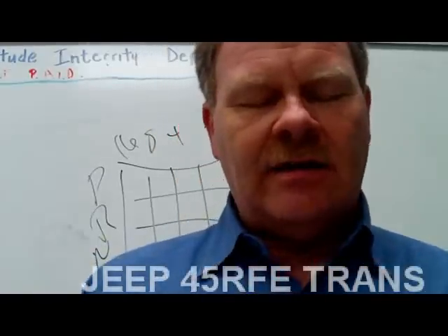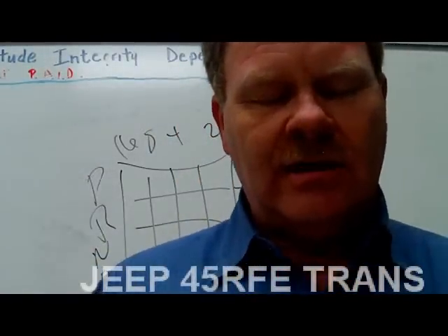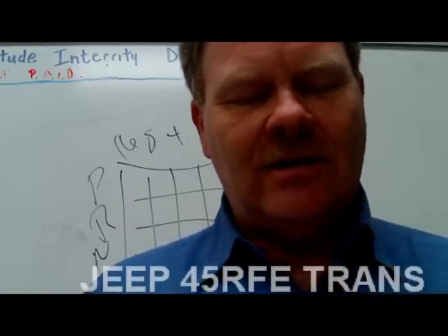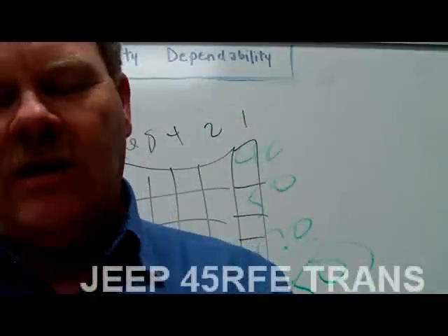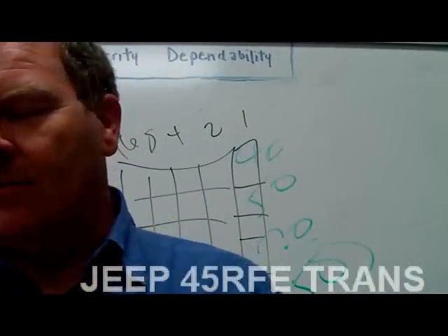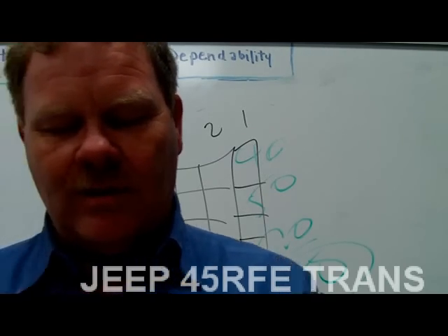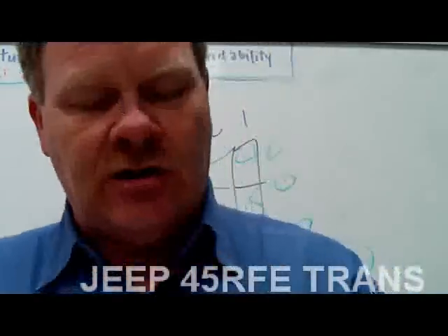All right, the solenoid pack of the TRS assembly consists of the transmission range and temperature sensors, pressure switches, and shift solenoids. The solenoid pack TRS assembly utilizes a 23-way electrical harness connector to link up with the transmission control unit. 23 wires go through that thing. The solenoid pack's got one pressure control solenoid and 6 shift solenoids.